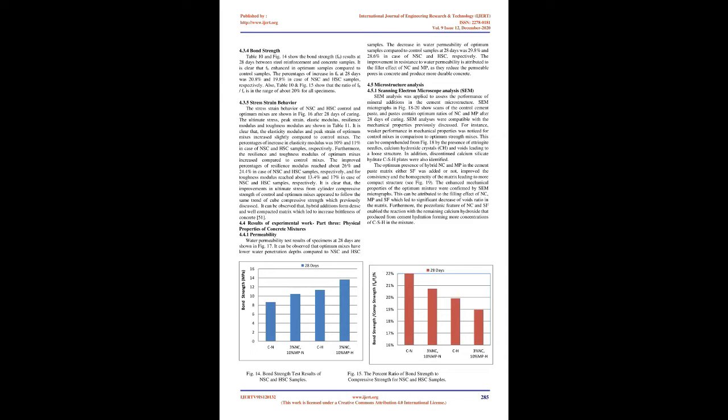4.3.1 Concrete compressive strength. Table 10 and Fig 9 show the development of FC for NSC and HSC control and optimum mixes. The same trend of improvement by using these additive ratios in HSC was noticed. The improved percentages of FC, compared to the HSC reference mix, CH, reached the range of 25% for all test dates. Moreover, it was observed that FC of NSC specimens, 3% NC 10% MPN, almost approached the strength of control specimens for HSC, i.e., CH, which indicated a significant improvement for the NSC mixture.